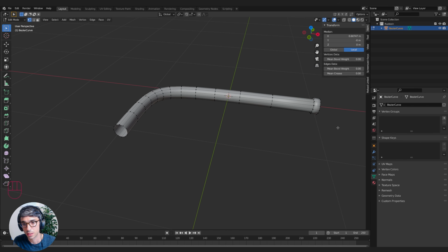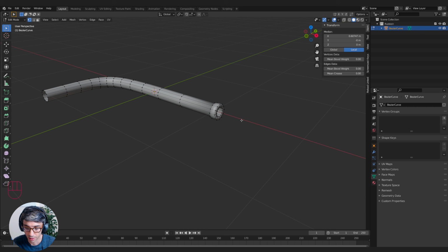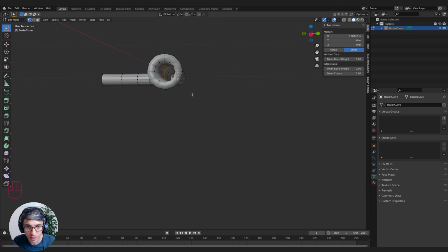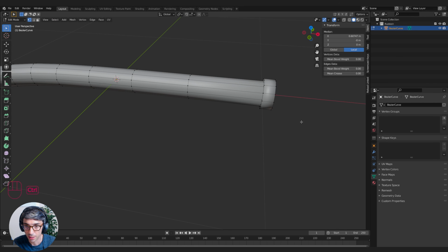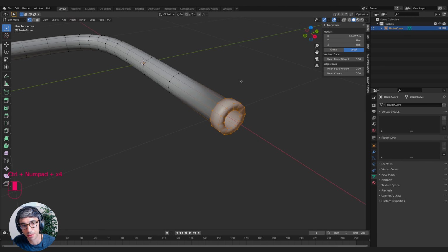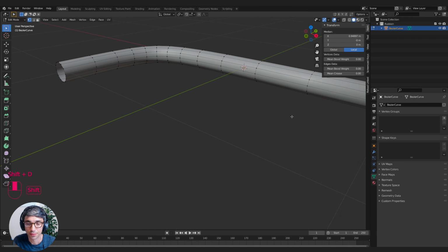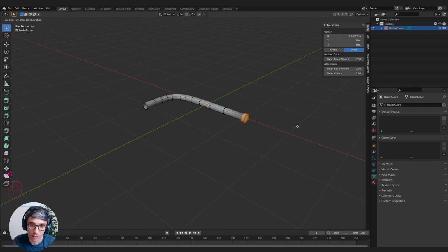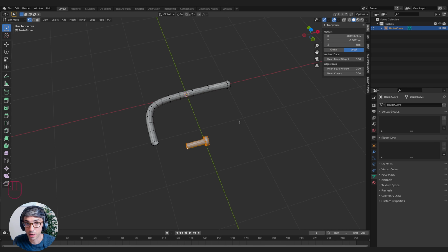And then I'll do the same thing, but instead of remodeling all that, I still have that one loop selected inside there. I can hit Control plus, boop, boop, boop, boop, like that, grab all of those, and then hit Shift D to duplicate. Now what I can do is I can hit G and Shift Z. You can see I've got this separate section. We're still in edit mode, so this is all part of the same object.